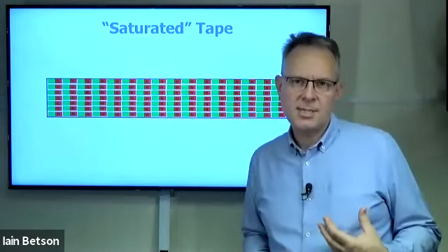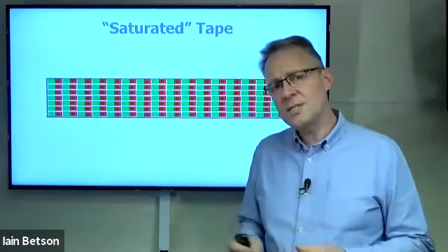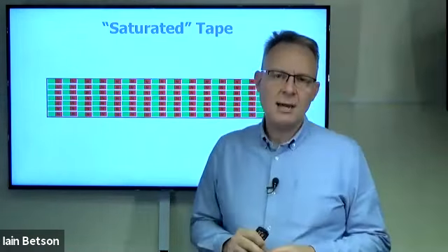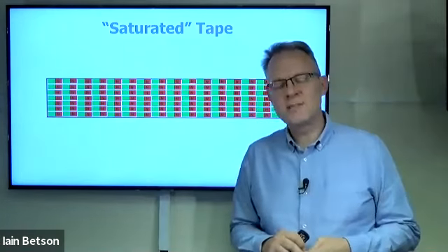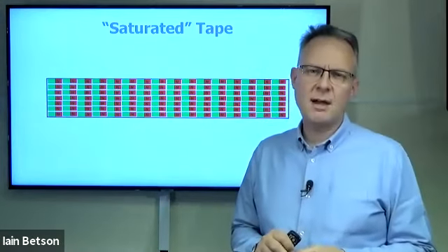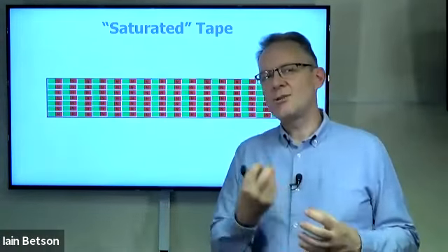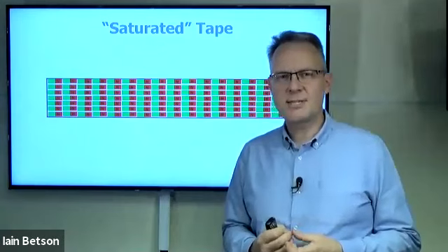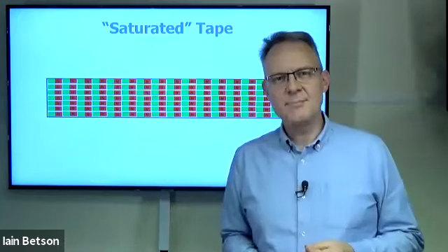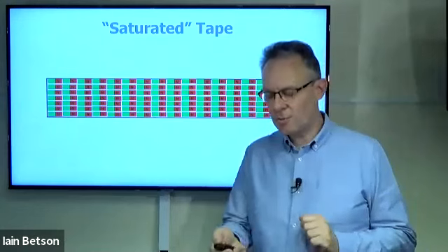Yes, we're talking about the 1960s, where perhaps tape formulations weren't as good as they were when they moved into the 70s, 80s and 90s, and therefore they could saturate earlier. But still, even tapes of that generation, and looking at the specifications of them back to ones of the 1930s and 40s, could easily take 1,200 to 1,500 nanowebers before they saturated. So it does make you wonder whether that saturated tape sound that you get on those Motown 60s records was more down to distorted electronics rather than the tape saturation. Who knows? But that's a kind of idea of how much level you need to put onto a tape to saturate it.